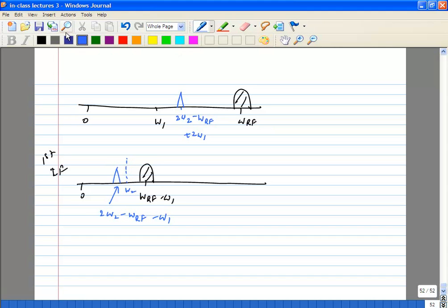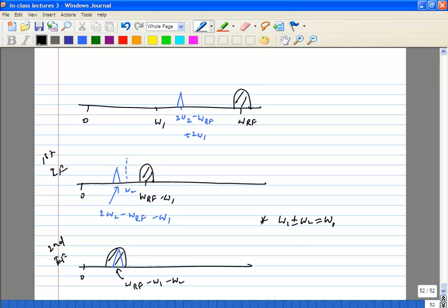And then at the second IF, the desired signal comes down to omega 2, and this guy is also going to come down to the same frequency. So what can you do to prevent this? The final output will be at baseband because you're going first omega 1 and then omega 2. Then you don't have the secondary image problem. So you have the first IF, then you go immediately to baseband. Okay, so let's stop here.